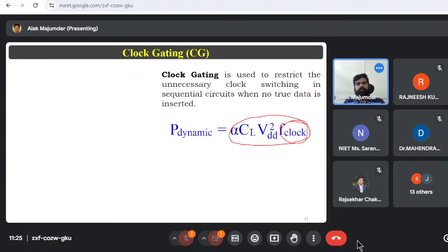Okay. Now the point is, just think, if the clock hitting is 100 megahertz, the amount of current it will draw. Now compare the frequencies 2 gigahertz or 4 gigahertz and think what current it will be drawing, right? Definitely current will be huge. From 100 megahertz to 2 gigahertz, it is almost 20 times, so your current will also be 20 times larger because it's a proportional relation between dynamic power and the frequency.